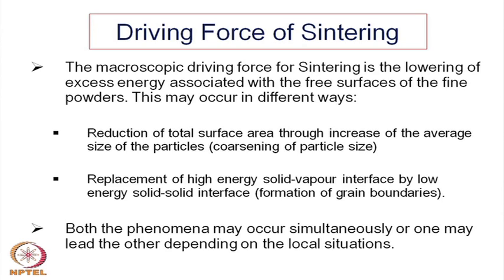When you compute the overall free energy of the system, it is dominated by the surface energy term compared to a solid material. So, compared to a solid material, powders have extra energy in the form of surface energy.